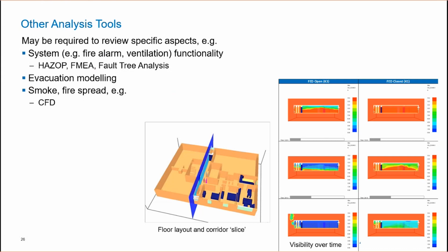We could look at evacuation modelling, modelling the flow of people through buildings, and see where the potential weaknesses, the choke points, exist. And also we can do very detailed modelling of how a fire might spread, and look at computational fluid dynamics, say, to tell us how the visibility, the heat within a corridor, and the oxygen might get depleted within an escape route.